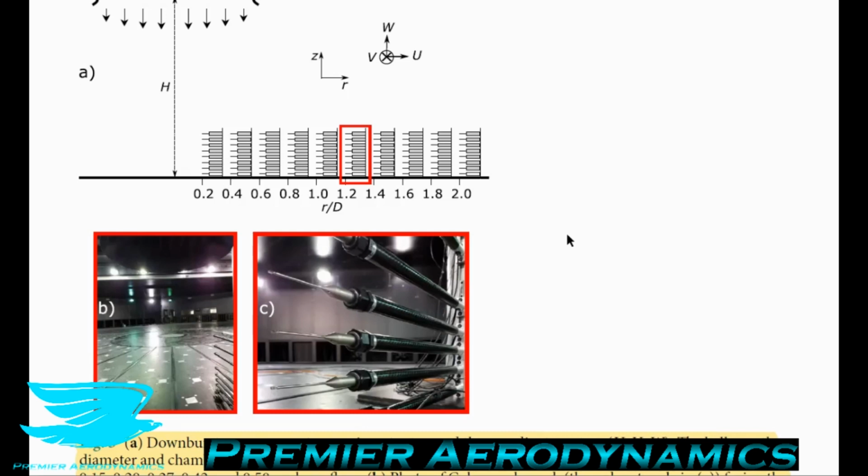And the reason why we have holes here is because each hole will, when you put it into the flow, register a different pressure. And this pressure can then be calibrated. We calibrate the probe so we know when the pressure in hole number 1 is X, hole number 2 is Y, hole number 3 is Z, then we can figure out, okay, well then the velocity is this. And we can figure out the 3 different components of velocity. That's what a multi-hole pressure probe is.